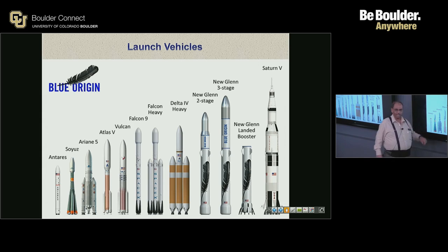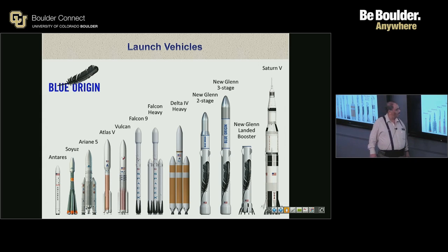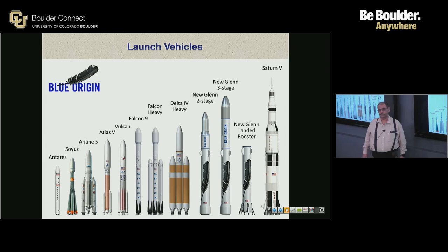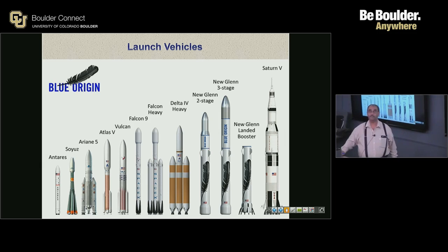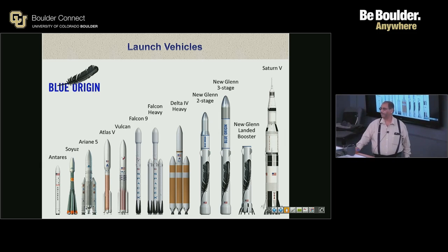And they are going to build Ariane 6. And interestingly, the way things go, they want to make Ariane 6 solid propellant in all stages. Why would they do that? Solid propellants have a lower performance, specific impulse, something like 270 seconds at sea level, whereas the cryogenic engine has 430 seconds at sea level. Why would one want to do that? Any idea? Yes.